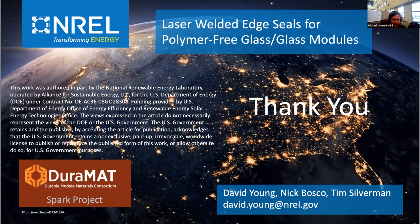So, this clearly has some potential implications for thin film modules and perovskites, which require a hermetic seal. Replacing the edge seal with laser weld could be a big benefit there. But tandems are also an emerging topic of interest, perovskite-silicon tandems in particular. In 4-terminal configurations where the perovskite isn't on the silicon, how do you imagine handling things like the optical matching between the perovskite and the silicon?